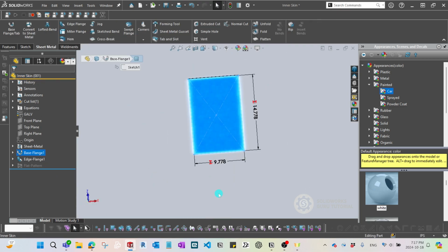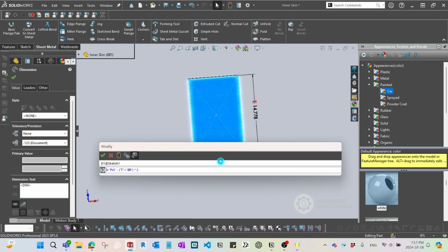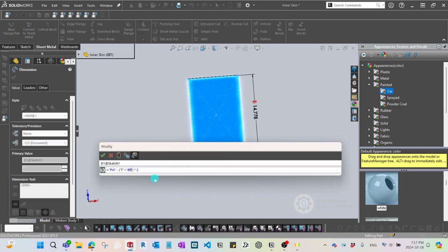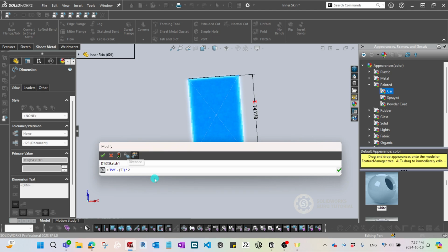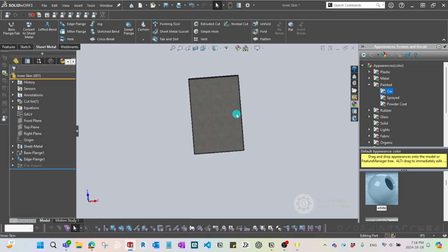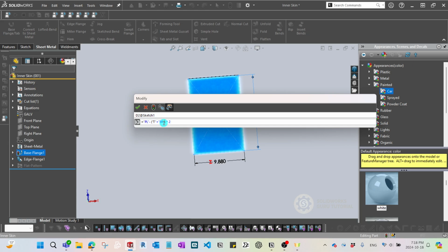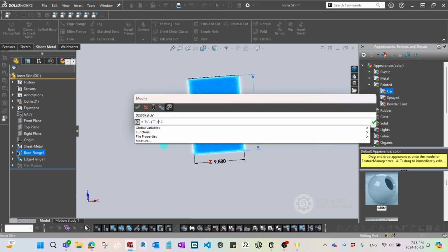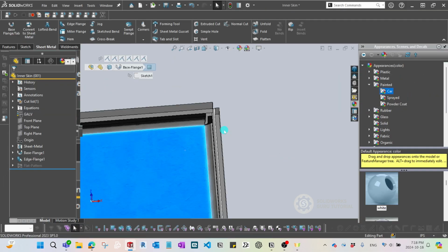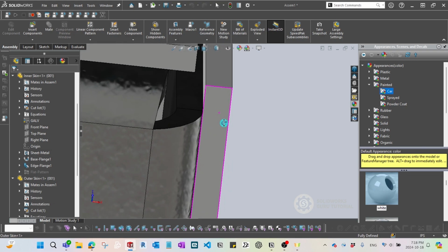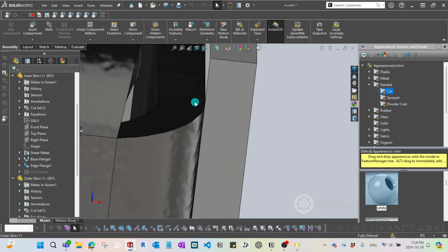So then the way you do it is going to be even simpler. You can just delete the bend radius and then delete the thickness, and then again for the height area I'm going to delete this thickness. It's perfect, and then you can press Ctrl B or Q to update the size of it, and once you come back, you'll be able to see this is perfectly touching each other.